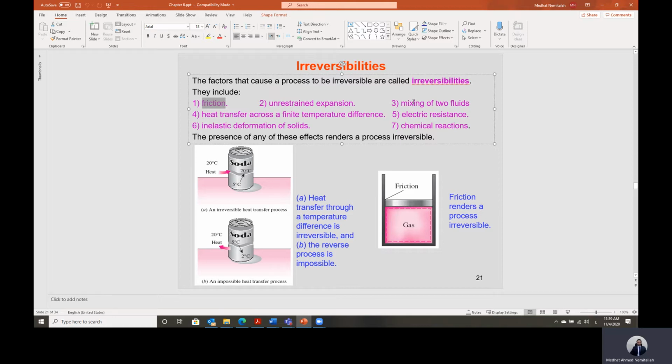In this case, we have to use a membrane system. Membranes are solid substances which are selective to a specific gas. Those membranes can separate the different gases, but to be activated for the separation, they have to be heated up to a certain temperature level. So that means we have to pay energy in order to separate the gases again.